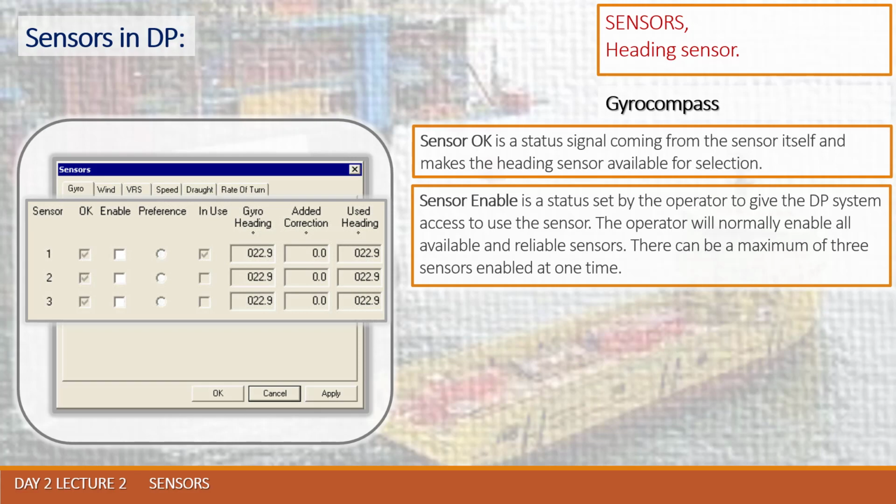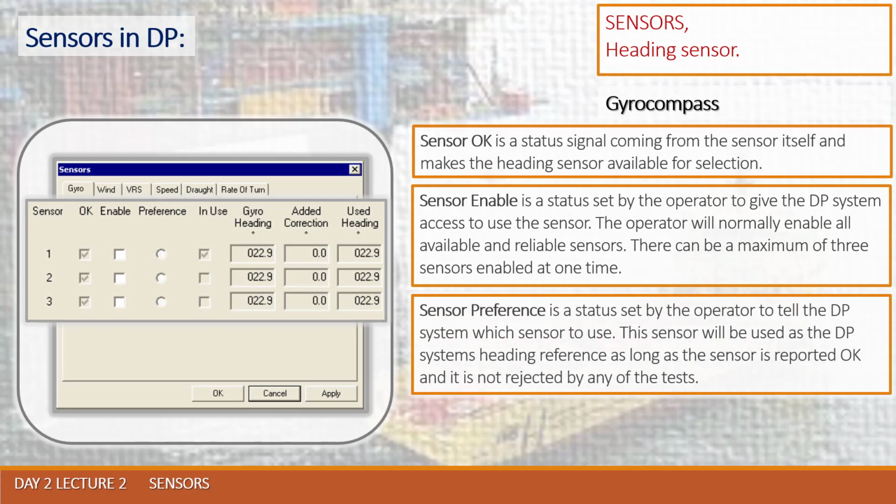When the DP system has the opportunity to accept the input of a sensor, the operator might give the preference for calculations. When we have more than one sensor, then the operator indicates which input from which sensor to give for the mathematical calculation to the DP model. So we don't have sensor pooling like in the PRS case.